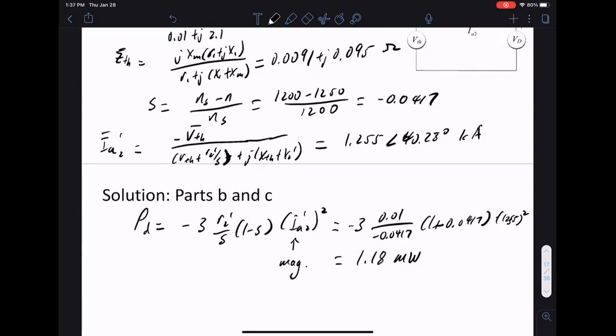However, when you compute the developed power and put down an imaginary part, you should recognize there's a bug in your calculations. That will be judged quite harshly when I grade the midterm or the final. So that's something to remember: square the magnitude. If you forgot, you should be able to tell that this is the wrong answer.